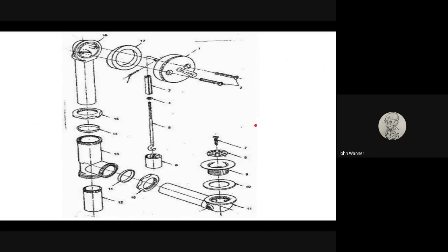Now, also in plumbing, you see this a lot in plumbing. This is called an exploded drawing. It actually takes a fixture or a piece of one and breaks it out in individual pieces and shows you the order of assembly, sometimes called an assembly drawing. So this is actually a drain on the tub. If you have a tub at your house, what you can't see in the wall, you can see this piece, which is a little control valve, and you can see the little strainer basket in this piece.